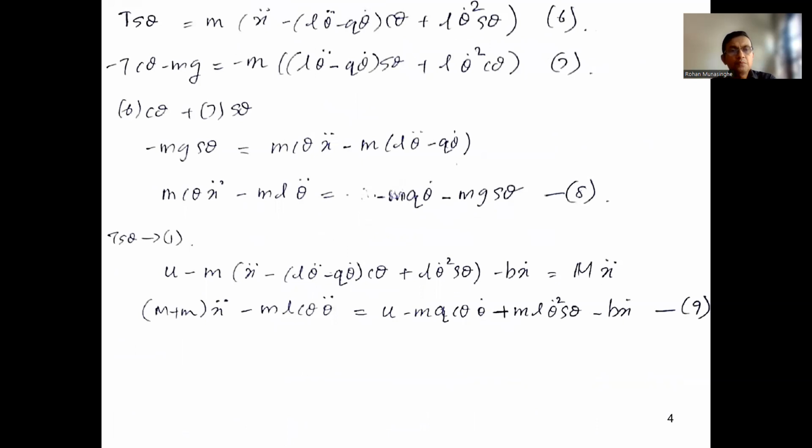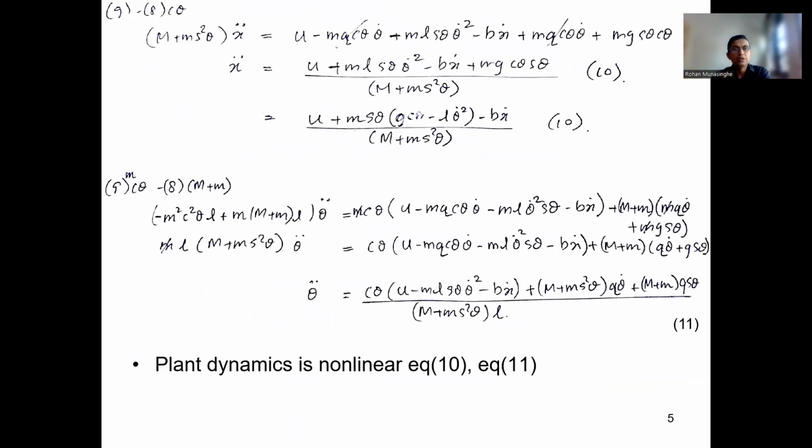So I think you remember these equations. For example, equation number 10 over here, x double dot. This is the acceleration of the cart at any position. You have the entire system over here on the right hand side. You can see U. This is the force on the cart, the control signal actually to the cart, because by driving the motors on the cart, you move it this way or that way, and you're giving a certain force there.